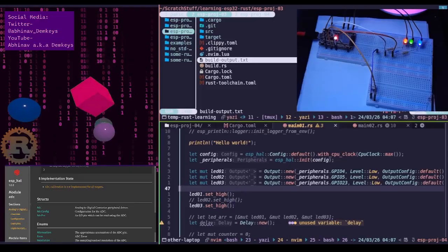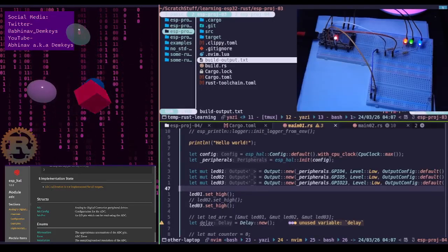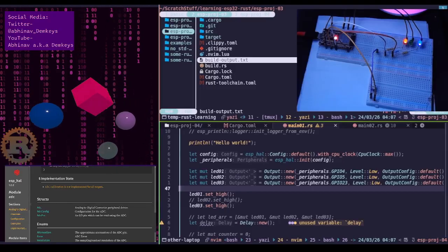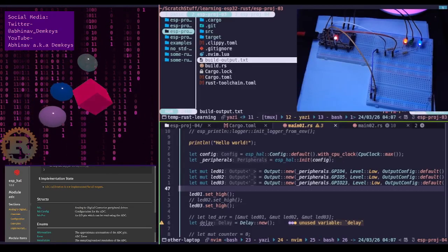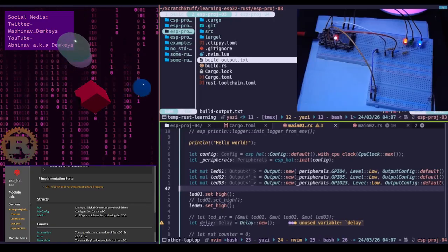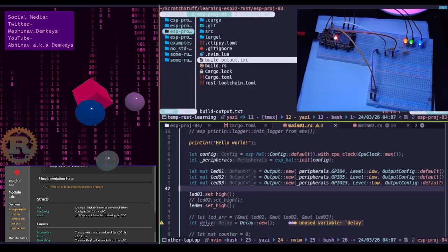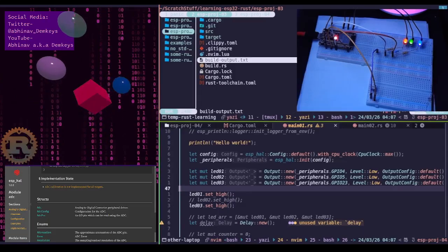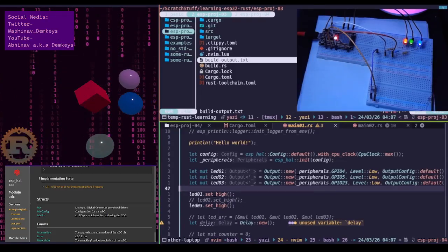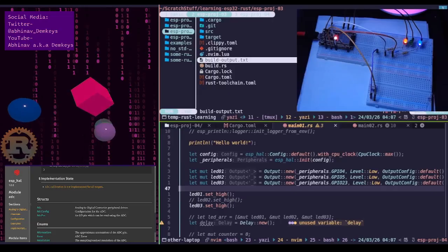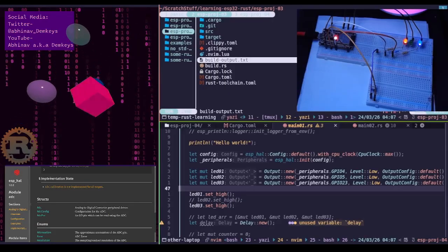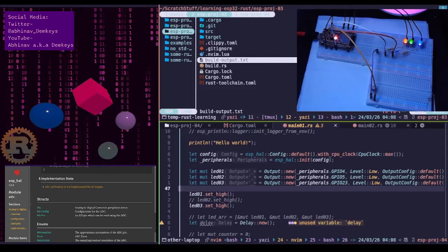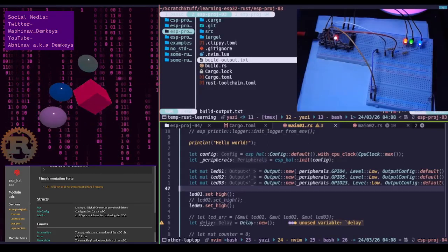If the slope is too steep, then a short increase in the voltage would give you a very high increase in the reading. So a short increase in the analog voltage would give you a very high digital reading. Then B is the y-intercept. This is the offset. If B is not 0, your ADC will say 50 even when the pin is connected to ground.